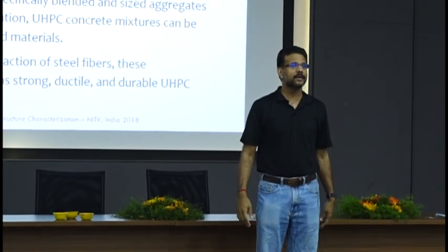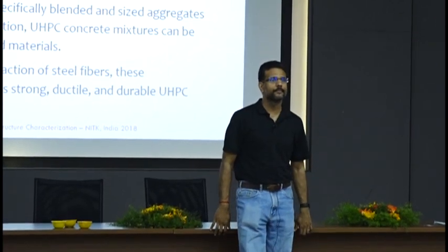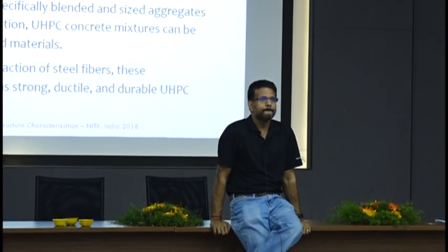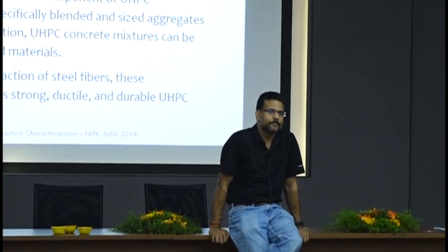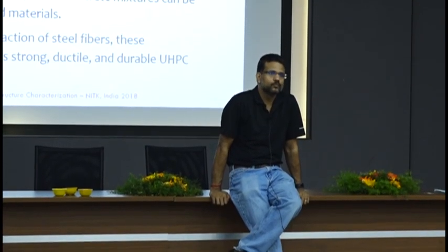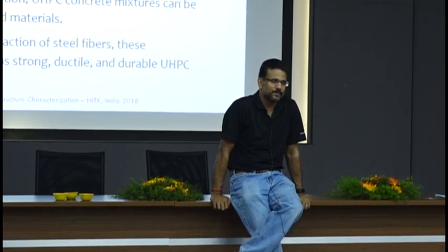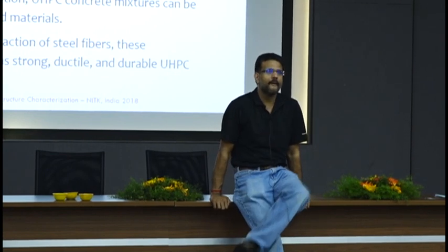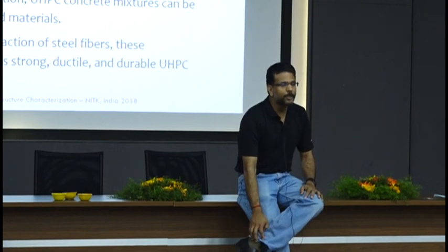Let the fly ash not react. Why do I bother? If it fills in the space and gives me strength, I'm good. As a filler material, this will partly help packing, we can do that. But the contribution of either fly ash or metakaolin to convert CH into CSH, how much is needed, or how much silicon dioxide is present? So none of these are exact sciences. People will fool you with this.